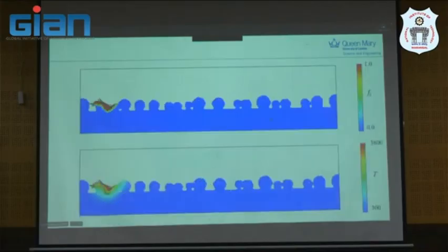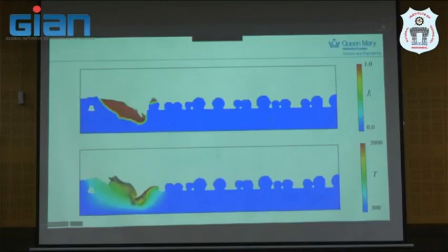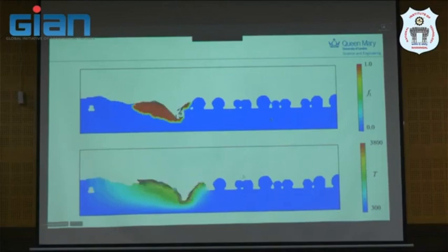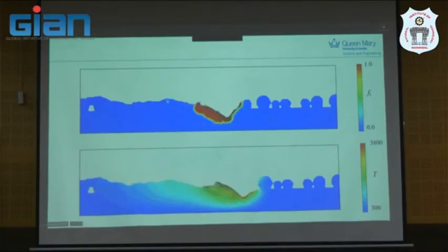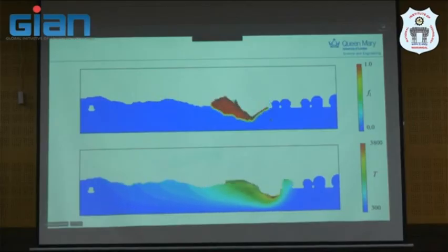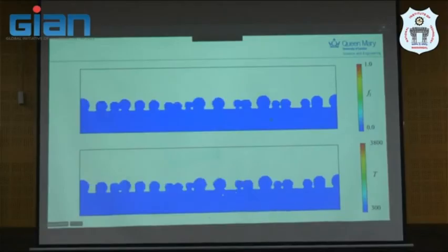The temperature, melt pool, and the velocity distribution are presented in these two pictures. The solid metal particles were gradually heated by the laser to form a melt pool, and the shape of the melt pool was basically stable after a period of time.